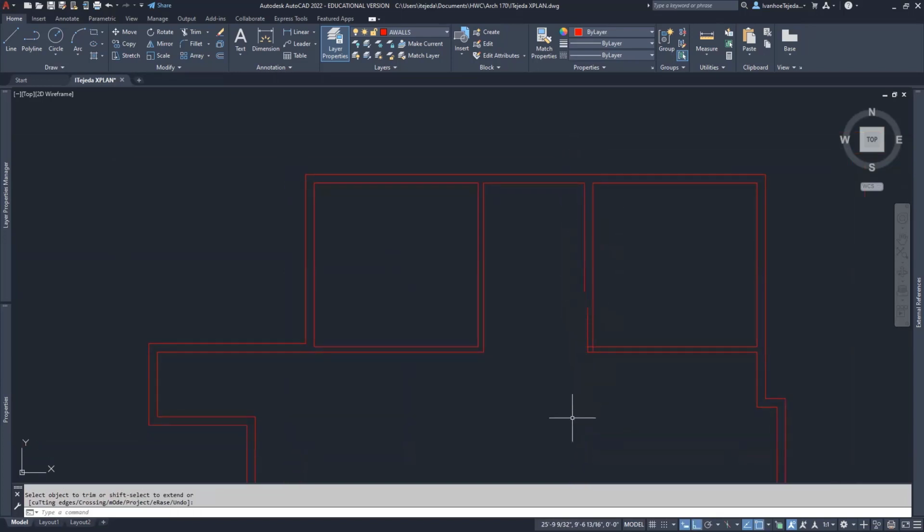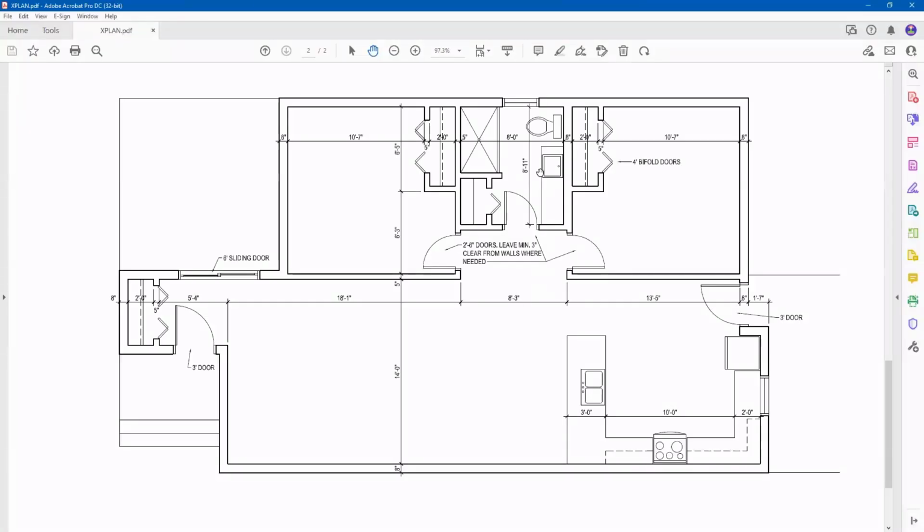And I think what I'd like to do, since I will be providing you with a bathroom, I just want you to outline the walls at this point. So if I go back, you can see that the bathroom is 8'11". There is no continuation of the dimensions here, and that's done on purpose so that you can think about this. And if it's 8'11", you know that the wall is 5 inches, then there's no need for this dimension because that wall is already in place. Typically in construction documents, we would provide that, but the reason I left those out here is to get you to think about this plan.